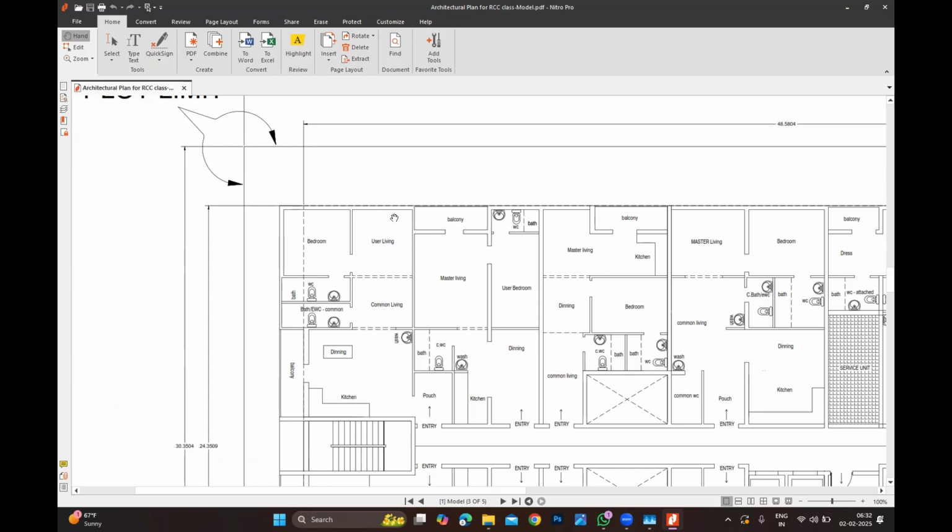To reduce the total weight, you only have two things in your hand. One is the self weight of the structure, another one is block load. Other than that, you don't have anything. Live load, can you change it? No. Seismic load, can you play with it? No. Wind load, can you play with it? No. There are only two in your hand: one is the self weight of the structural element, and the second one is block load.